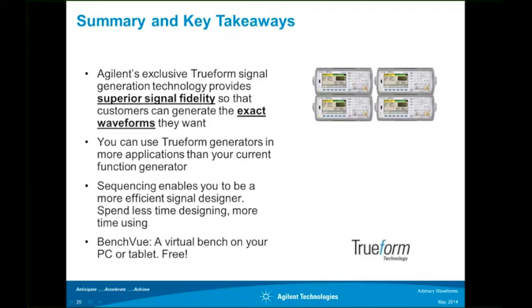So sequencing is going to allow you to be more efficient, not only when you're designing your signals, but also when you're using your signals. You can smoothly go from one signal to another with triggering capabilities or repetition rates. So that's going to allow you to save time when you're configuring your signals. You no longer have to download a new signal to your arbitrary waveform to get a new signal. You can just use sequencing to go to your next signal.